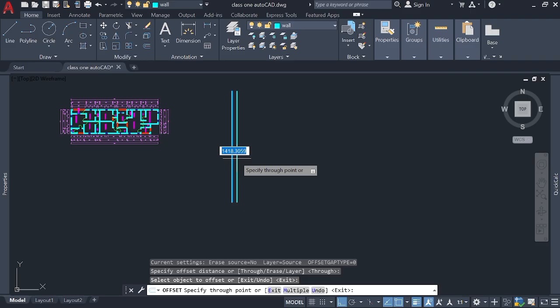Alright, 150 millimeters is the same thing as 6 inches, approximately. While 225 millimeters is approximately 9 inches, in case you're using inches. And while molding your block, you will know the type of block you're using, whether you're using a 6 inches block or a 9 inches block. Note, the block you're using is going to be a hollow block because it's downstairs. You're not building a bulletproof, or you're not designing the foundation that you need a block without hole.